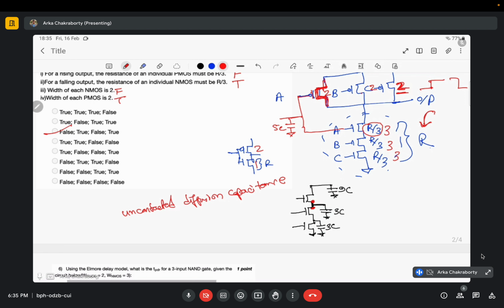If after this first transistor there was a metal layer, then I would have got this 3C plus 3C as 6C. But what they do is design only one N plus or P plus region for both these transistors. So this region is common between them, and there is no metal layer present between them, that is, there are no contacts between them.